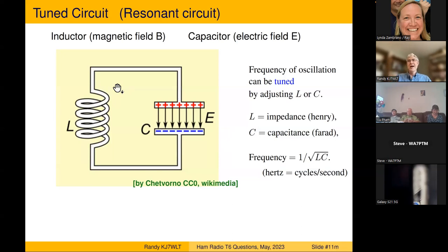So as you turn the knob on your tuner on your radio, what you're doing is basically adjusting the amount of inductance the inductor has, and that changes the frequency at which this wants to oscillate. And now if you hook it up to an antenna, the antenna is giving some energy input, a very small amount of energy, but as electrons move back and forth in the antenna that were set in motion by the electromagnetic waves, the radio waves propagating past the antenna, there's radio waves propagating past the antenna at lots of different frequencies, all sorts of radio sources that are hitting your antenna.